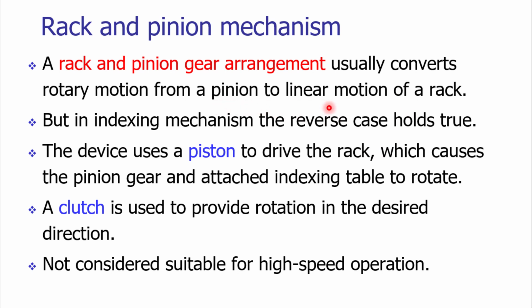We are providing linear reciprocating motion of the rack, or we can have straight one-direction linear motion to the rack, and that should be converted into the rotary motion of the pinion, and we are attaching the work table to the pinion. So as the pinion is rotating incrementally, we are getting the indexing of the table which is connected to the pinion. In this way, we are getting the indexing of the table which is attached to the pinion by the linear motion of the rack.